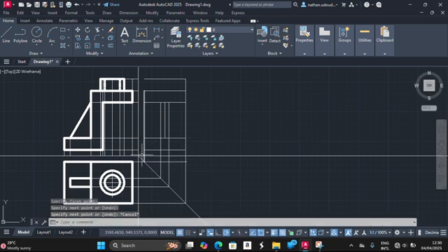So the combination of the lines you trace from your plan, your front elevation and the plan, will eventually give you the side elevation. So it's either you transfer all the lines from this point here to this inclined line, and you now transfer them up. Or since you already know the measurement from the given diagram, from this point you can trace out the diagram.